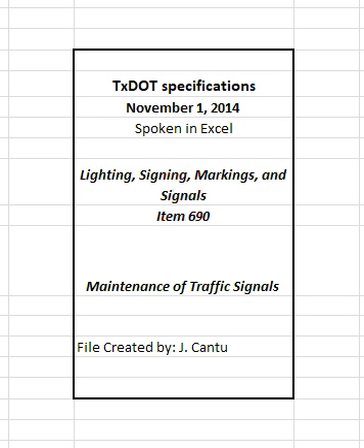Measurement will be as follows. 5.1 Removal of conduit. By the foot of conduit. 5.2 Installation of conduit by trenching. By the foot of the trench containing conduit, regardless of the size of conduit. 5.3 Installation of conduit by jacking or boring. By the foot of road bore made. Pits for jacking or boring are subsidiary to this item.